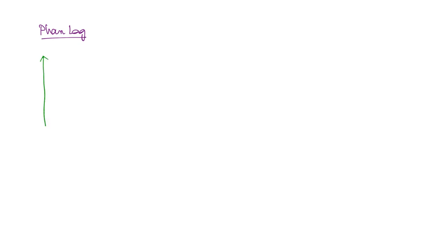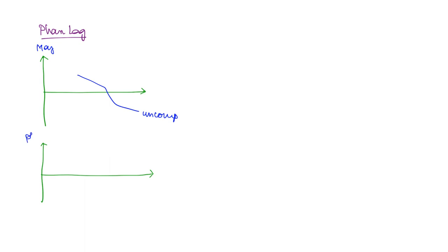So we will start with the magnitude plot. This is the phase plot. Now here what is going to happen? If this is the uncompensated plot, you can write down here, this is the magnitude and this is the phase plot. Then what will happen if there is a compensation? The magnitude will reduce because this is a phase lag compensator. The magnitude Bode plot of phase lag was negative, right? So the compensated system is going to be like this. And this is the new gain crossover frequency omega g dash, and this is omega g.